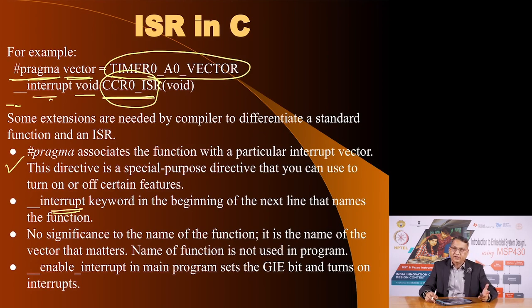Of course, it should not be a reserved keyword or anything else. Once you write this in your C program, you must thereafter write the subroutine associated with this label. Now, void here means you are not passing any parameter to the subroutine, nor is it passing any result back to you. Then how does the interrupt program help you? Through shared memory locations, variables. So, we will see how that is handled.